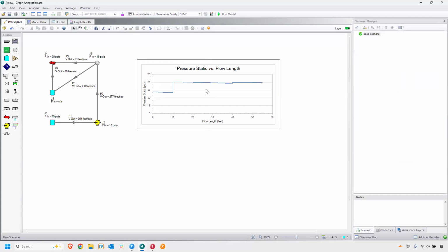Lastly is the replot after run. When we do this, normally the graph will update automatically when we're building out our model and when we're rerunning it. But sometimes if you have a larger model, this can take extra time to actually generate the graph and maybe force your software to load a bit slower. So it can be helpful to potentially turn this option off so you can only graph these things when you are ready to look at them.